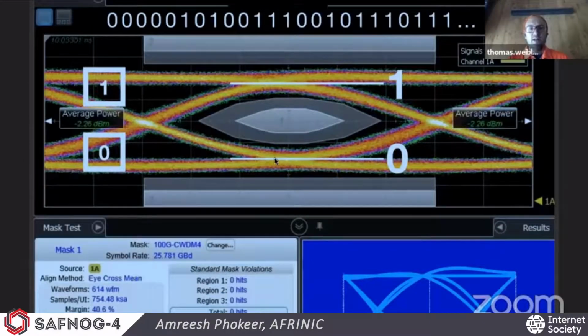And what makes an eye is this shape in the middle. And this shape is really important for an eye diagram. So we got those 2 events, 0 and 1, seen on the right side. And we really want to make sure that the high-speed signal doesn't cross that shape in the middle, because when it would do that, the receiver on the other side couldn't detect if it's a 0 or a 1.